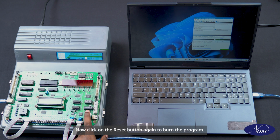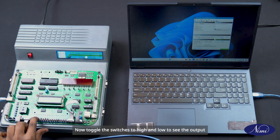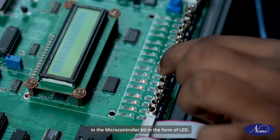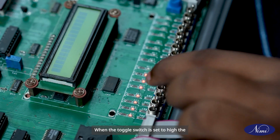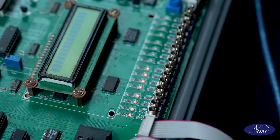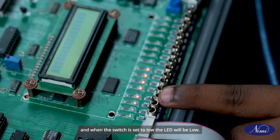Now click on the Reset button again to burn the program. Now toggle the switches to high and low to see the output in the microcontroller kit in the form of LED. When the toggle switch is set to high, the LED will be high, and when the switch is set to low, the LED will be low.